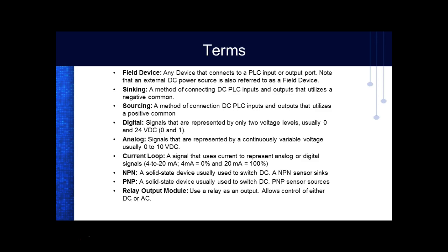One additional benefit is that if you've got 0 milliamps, that tells you you've got an open circuit. Yeah, and that's one reason they never use 0 to represent a 0. They use a current, because it's impossible for EMI to generate a current. So they use a current flow for a 0, and they use a current flow for a 1. If it doesn't have any current flow, you've got an open. Then of course you see the maximum output. But the biggest advantage of current loop is that it's impervious to electromagnetic interference. You'll run into that a lot, especially in instrument systems.